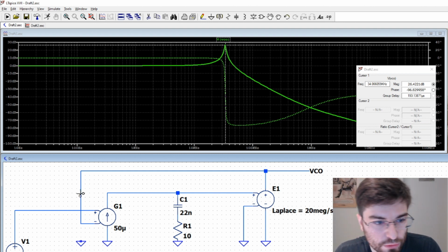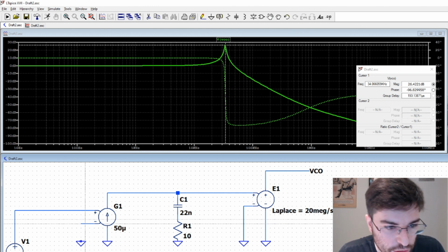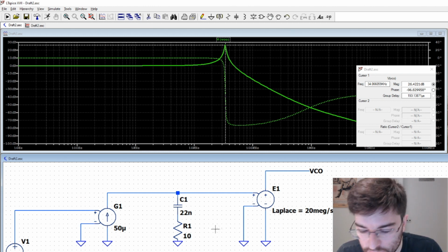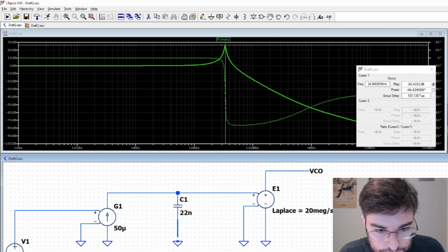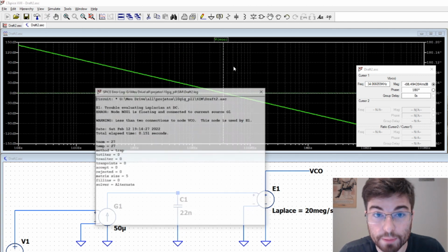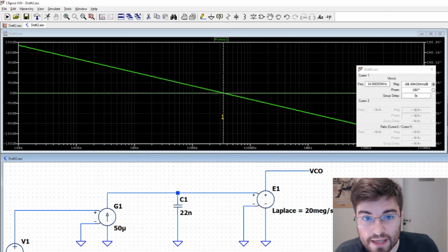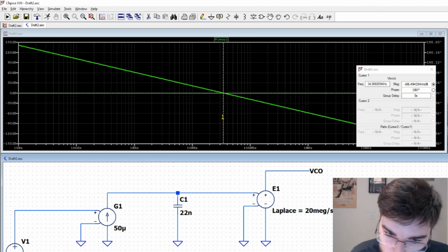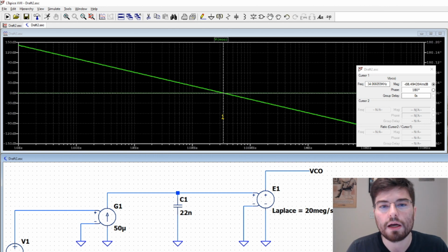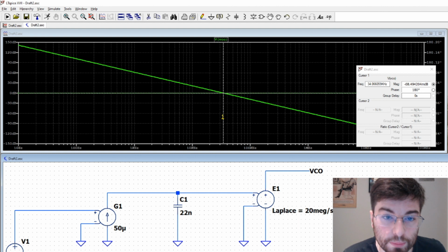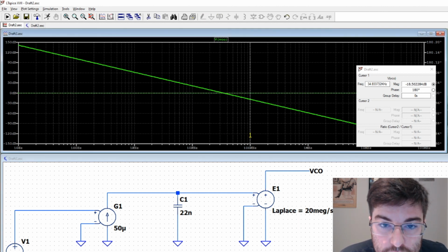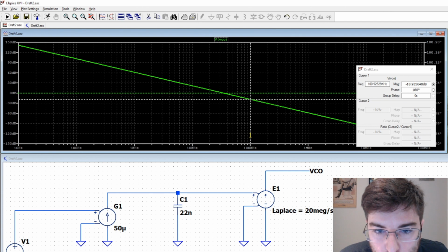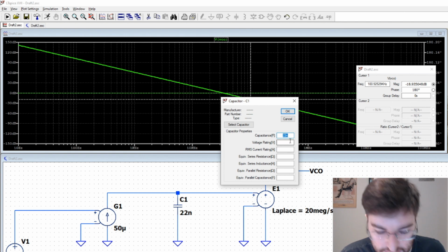So what we're going to make now, guys? First thing we are going to make is that I want to open a bit the loop bandwidth, okay? So we saw that the 3 dB point of the closed loop filter response of the PLL will be very near, almost coincident with where we cross 0 dB in the open loop. So I want to cross 0 dB closer here to 100K.